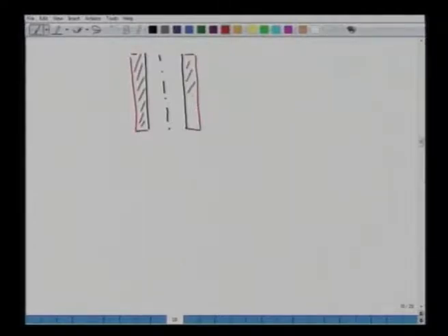It is given as 4 inch, and here this is 2 inch and this is also 2 inch. This height is given as 36 inches. This temperature is Ts, the environment temperature is 78 degree Fahrenheit, and this temperature is 1200 degree Fahrenheit. So, we have to see whether this 2-inch layer thickness is sufficient or not.